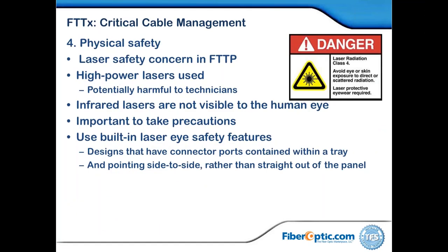The other is physical safety concerns. Since there are high-powered lasers from the central office, they can be harmful to technicians. And since they're not visible to the eye, you must take precautions, like built-in laser eye safety fixtures. They can be designed with the connector ports contained within a tray, or connector ports which are angled out or fold out, so that at any given time they're not within the line of sight of a technician working on them. And that's what I mean by the point-to-point.